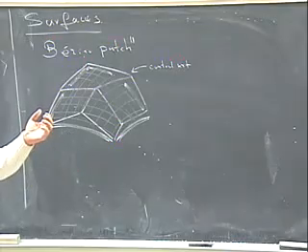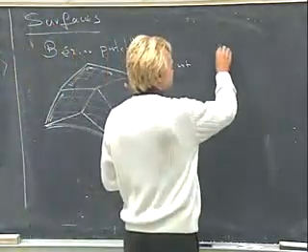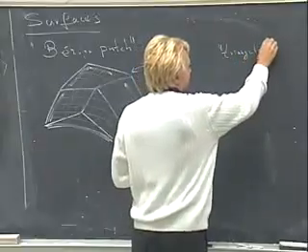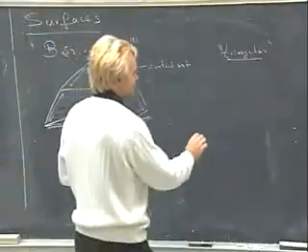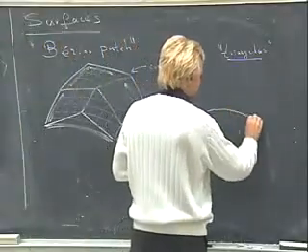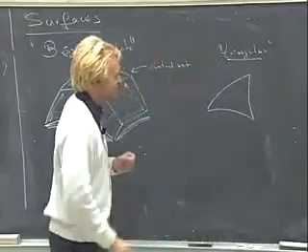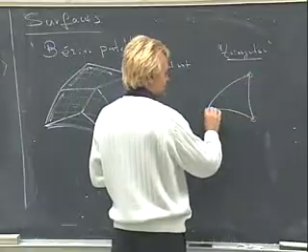No, it's not. I can do one with 3 boundary curves, right? So there is also something called a triangular Bezier patch, which has 3 boundary curves. Okay, so I can do this, of course. Curve, and curve, 3 boundary curves, and the control polygon living above it looks like this.